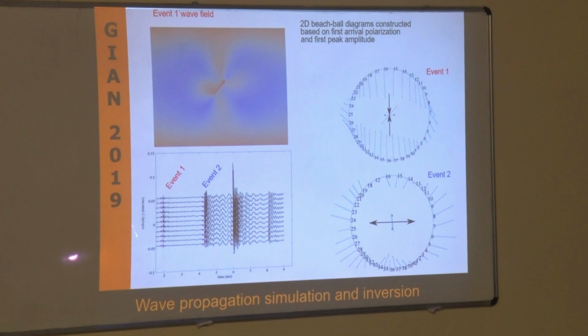Was the behavior the same? Was the way it failed the same? No. One was a scatter, all vertical cracks, and the other was a nice, neat, oriented fracture at, whatever, 18 degrees, 75 degrees, right? What did you change then? Just the boundary conditions that rock was experiencing, and the behavior of the rock was totally different, right? So that was an emergent property, an emergent behavior.